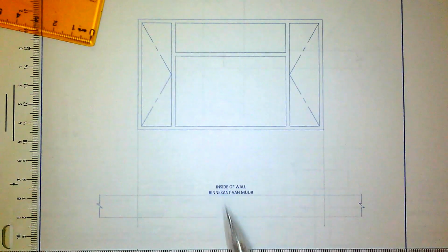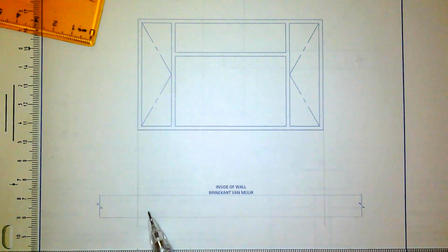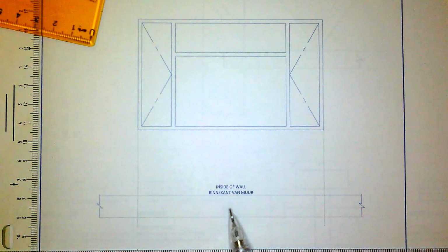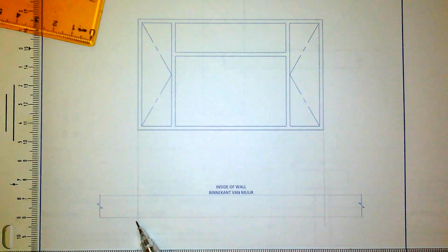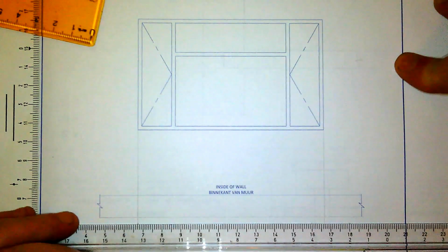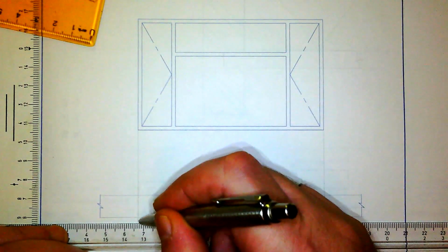So this is the inside, so this would be the outside of the building. So there would be your lawn, there would be your carpet. Okay. And the only rule here is that when you add the sill, you have to add a slight thickness to it. Now normally the window is never drawn this big. We're talking about a symbol for a window that is very, very small normally on a floor plan. Okay, and then the sill can just go over half or 1 millimeter. In this case I'm going to go over 2 just to keep it a bit more proportional. So for today's exercise, whenever you see the black pen, those are dark lines. Alright, so I'm just going to go and immediately add the sill as a solid line.